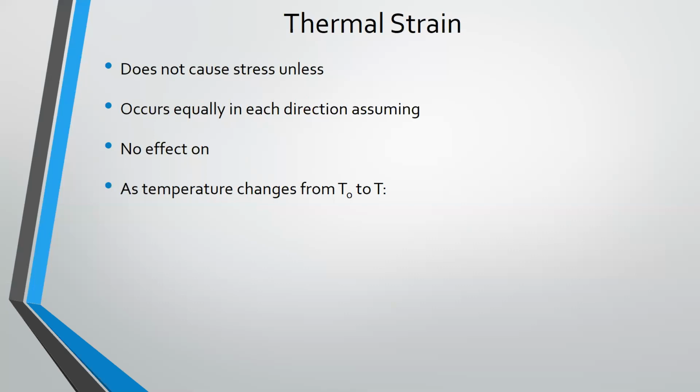Then same thing happens if it's trying to contract, and perhaps it's attached to a rigid boundary, and so it can't contract. Now you're putting tensile stresses in it that are going to want to cause it to tear apart, tear away from the constraint. So unless deformation is restricted.